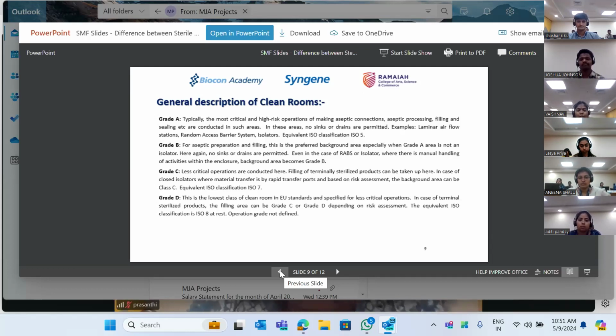Usually this is the way it is done. ISO class 5 is the cleanest classification and is used for critical areas where the product is exposed to the environment, such as filling zones for vials and ampules. These are done under class 5. The equivalent in EU GMP is grade A. So that's where I had to refer to the earlier lectures. The air quality in this area must meet stringent requirements for particulate and microbial contamination.